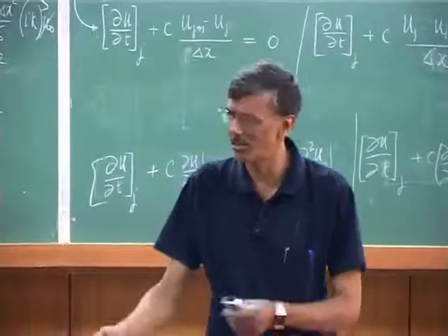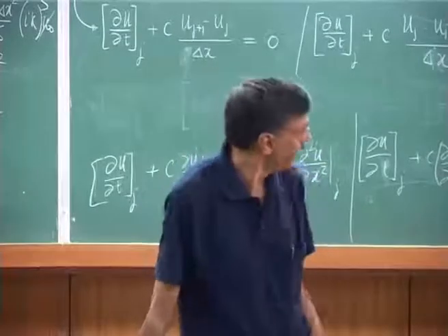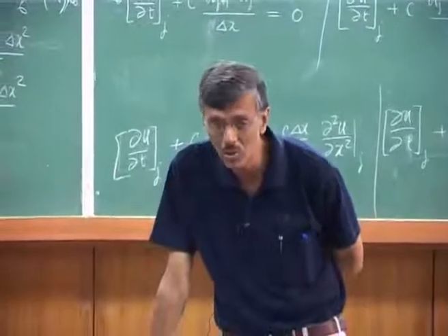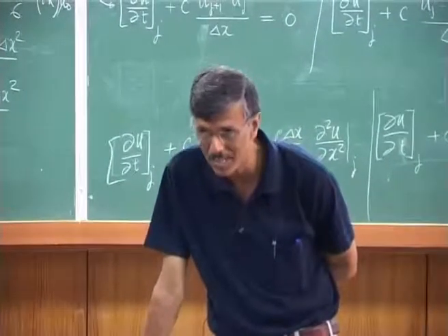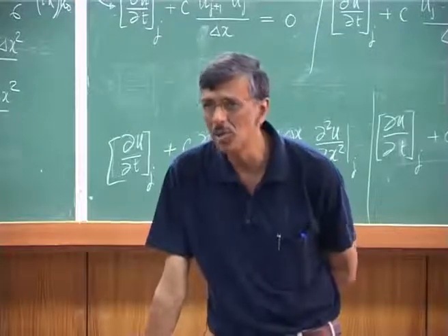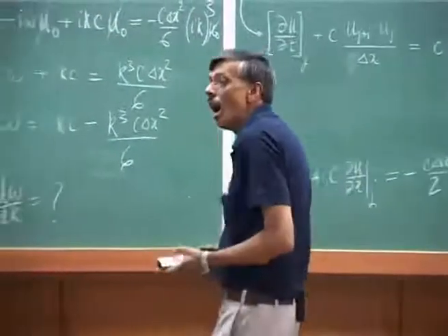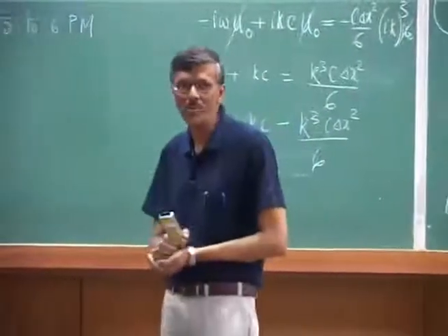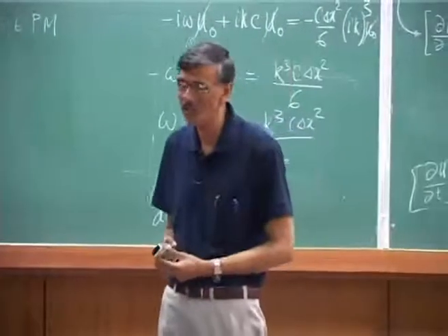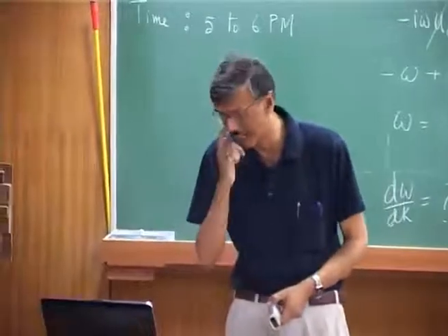What is stable and what is unstable, we will discuss in the very next class. Then how do I rectify? The rectification can come through selective explicit addition of an even derivative term, and when you do that, this is what we call upwinding. Basically, we are creating a proper bias to the solution, okay? And that is what we will be talking about in the next class.